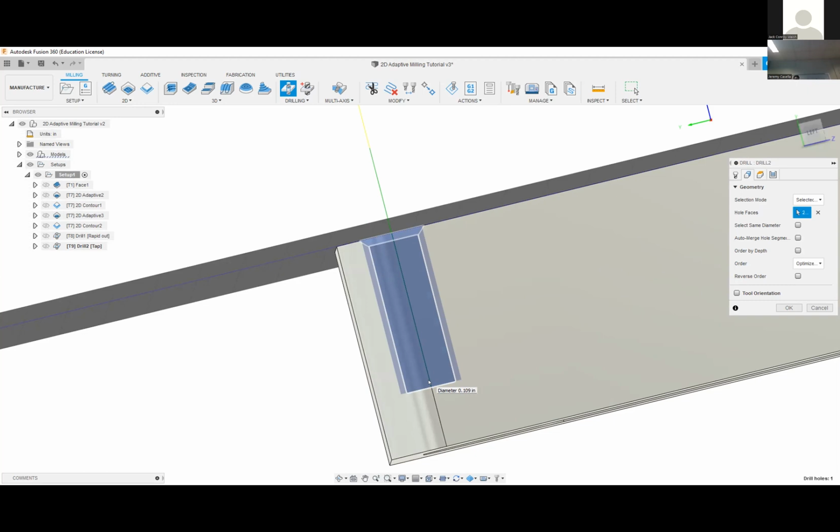When you design a part, it's not easy for people to tap to the entire depth of your hole. So as a design engineer, keep in mind, maybe I'm gonna leave that hole deeper and the threads will go the whole length in my design, but they're actually just gonna tap maybe here. So we'll leave 0.15 there, or maybe we'll make it 0.05, something, not nothing. We don't want it mashing against the bottom.